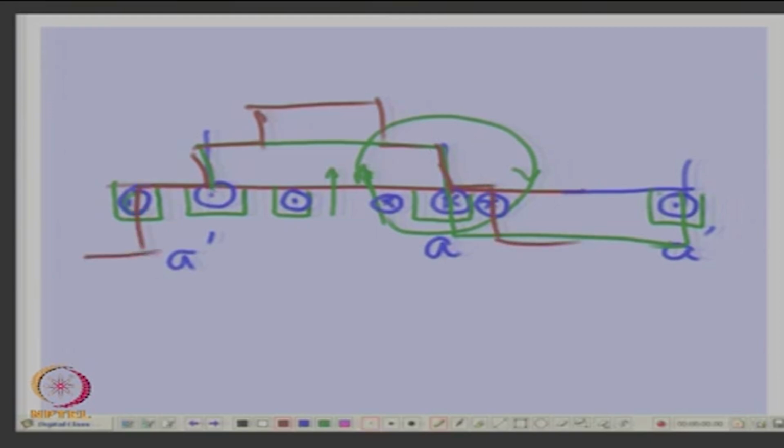So, it will be a stepped wave if you have more coils. One coil is like a rectangle, but superposed rectangles are displaced by the slot angle, right. So, you have one rectangle, maybe another rectangle, like this. Add them, and you will have a cumulative stepped wave. Is it clear?